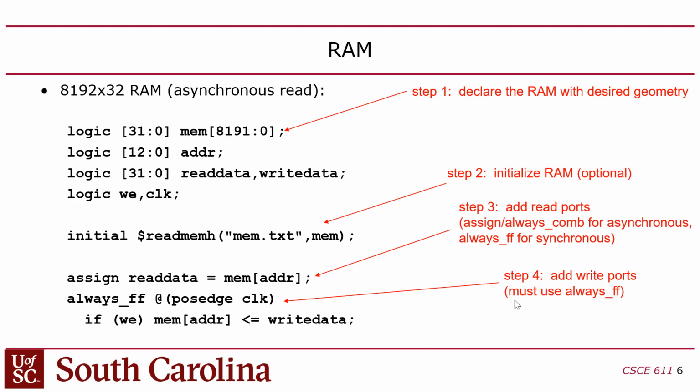Sometimes those ports can be restricted to just being able to read, or sometimes they can read or write, or read and write. It all depends on how you code it up. And then once you code it up in Verilog and you synthesize it, you hope that there's some primitive circuitry on the FPGA that will be able to implement that behavior. Now, in the case of the register file, I talked about how that has to have 3 ports on it, 2 read ports and 1 write port, which matches the instructions, right?